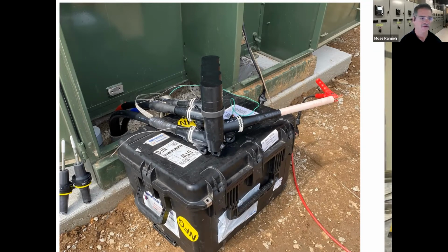And I should also mention, just because there's dirt in this picture, that the grounding system is another area where a third-party independent testing company might be of service to you, even if you're getting manufacturer testing, because in a lot of cases, the manufacturer's testing their gear, not necessarily all of the system. And part of what we want, of course, for arc flash safety is a properly grounded system. And that starts with the rods and copper that they put in the dirt to make sure that there is an earth connection.